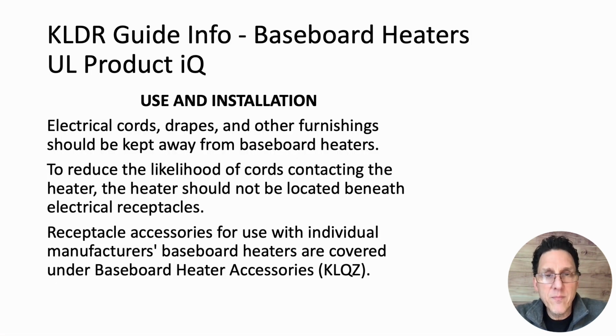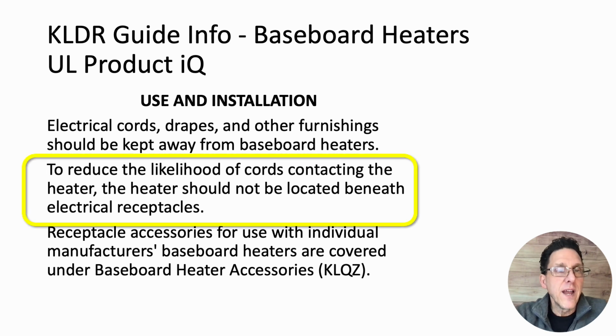All right, and this is from UL's website about its information for electric baseboard heaters. And look at the second paragraph up there. It says, and this is under use and installation, right? To reduce the likelihood of cords contacting, the heater should not be located beneath electrical receptacles. Now, remember, that heater has to be installed and used in accordance with the instructions.